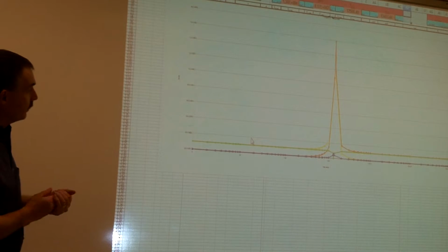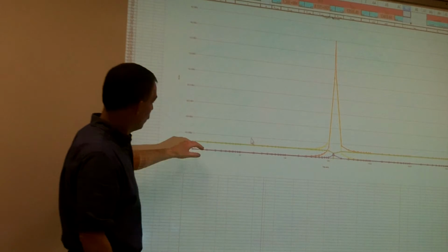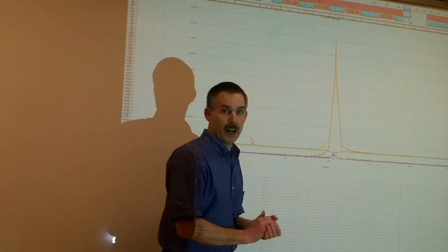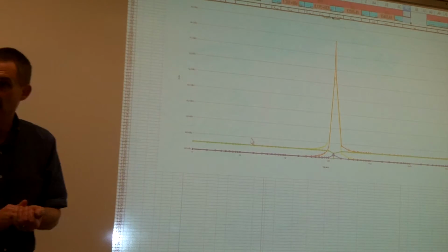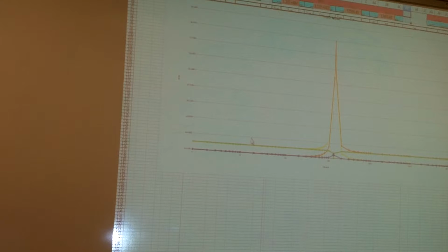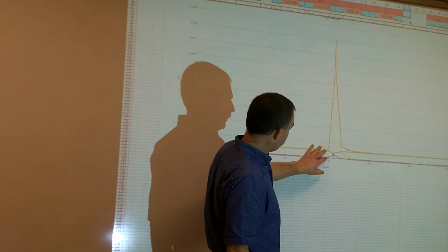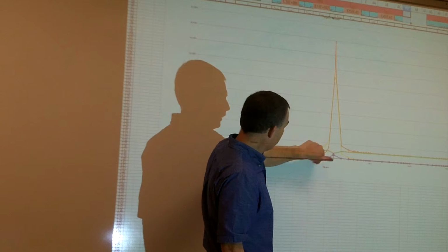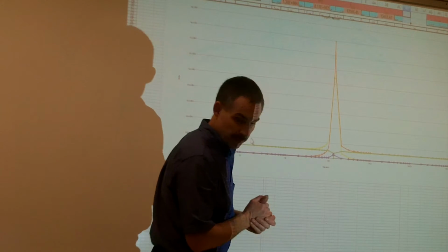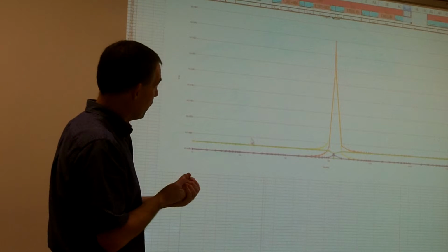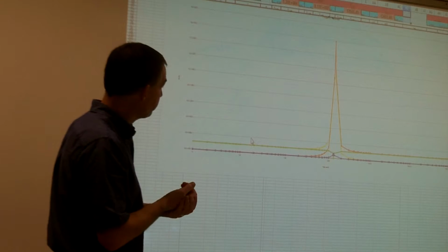Since I have such a large amount of resistance across the windings of my transformer, my inductor, I'm going to lose almost half of my voltage across my resistor, because a lot of it's dropping across that inductor, because the resistance of that winding was 30 ohms compared to 47 ohms. So I would just have to make sure that my amplifier is going to be very selective. I want to make sure that I'm at 70.7% of whatever my total voltage is across my resistor.